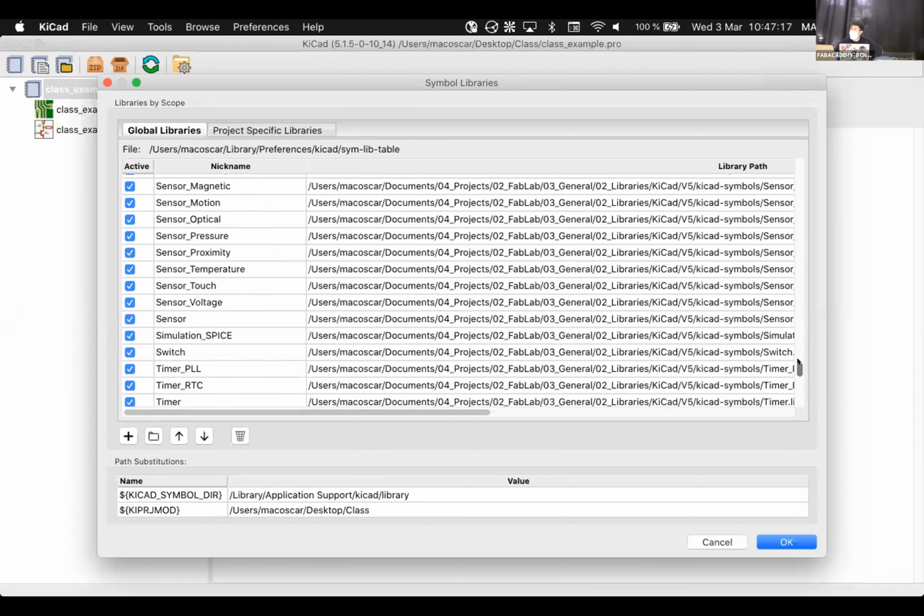They just download KiCad. They click on the symbol libraries. They are asked if they want to copy something or start from zero. So here we have to tell them to use the second option, that it's okay. They create an empty symbol library.